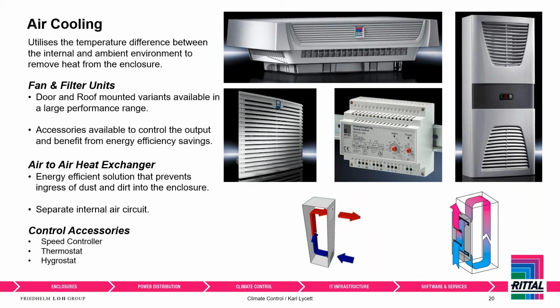So things like a thermostat, which obviously you turn the dial and select your set point, and then it will click the fans in and out when needed. The hygrostat does the same thing, but it looks at the humidity. So if humidity is of particular sensitivity for you, hygrostat is your man. And then the speed controller. Now this is sort of a bit more advanced.